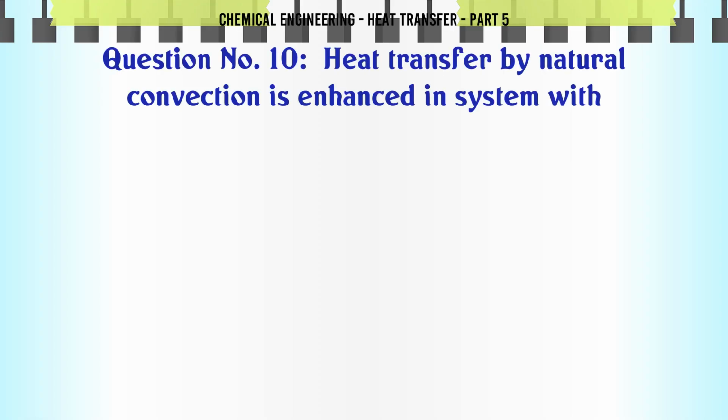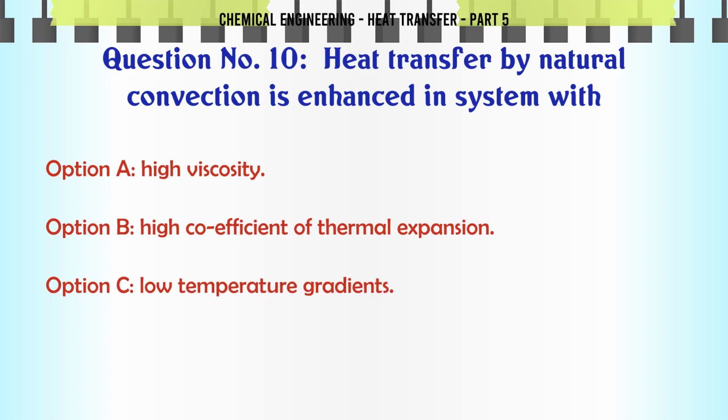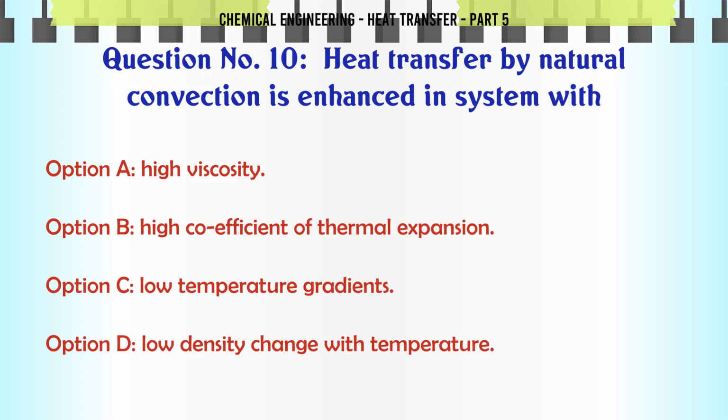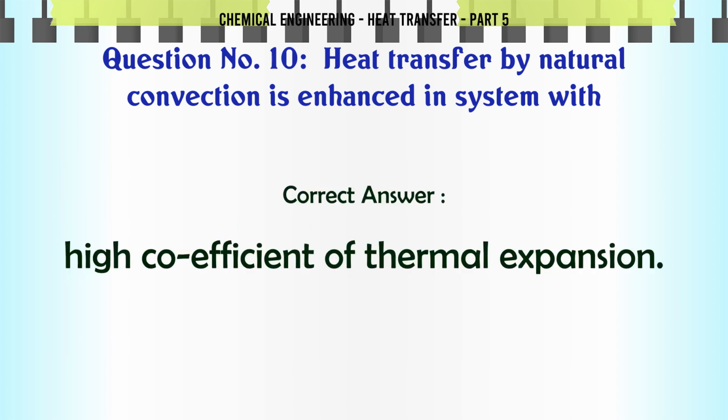Heat transfer by natural convection is enhanced in a system with: A. high viscosity, B. high coefficient of thermal expansion, C. low temperature gradients, D. low density change with temperature. The correct answer is high coefficient of thermal expansion.